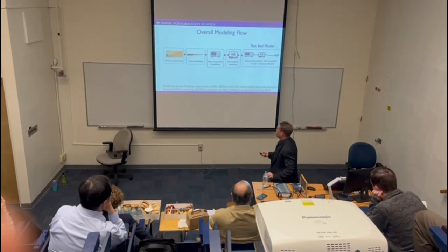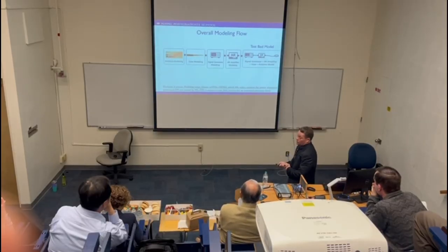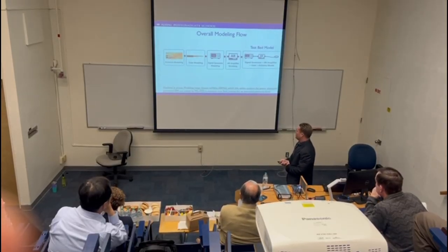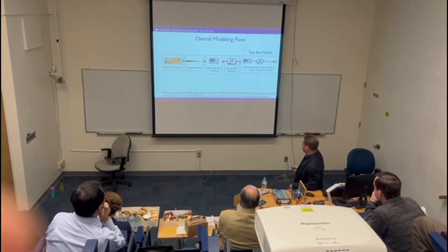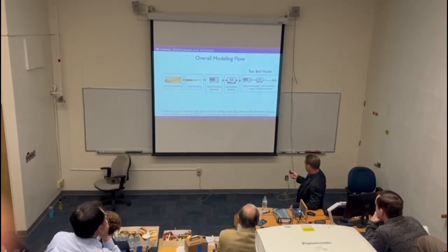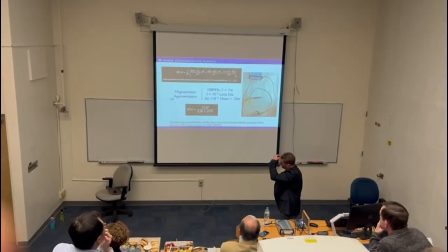Again, we chose the range between 1 megahertz and 100 megahertz because this falls within the modern day power electronic EMI that is not really directly captured in the electrical standard, making this a very important range, which brings me to a few assumptions.